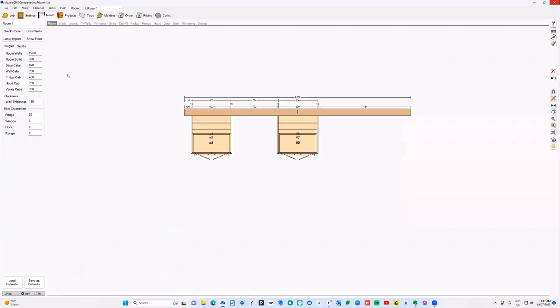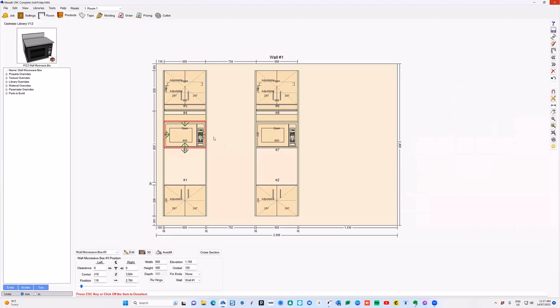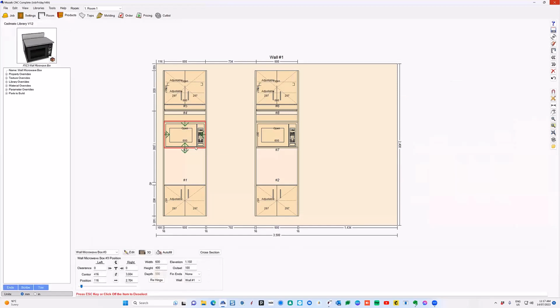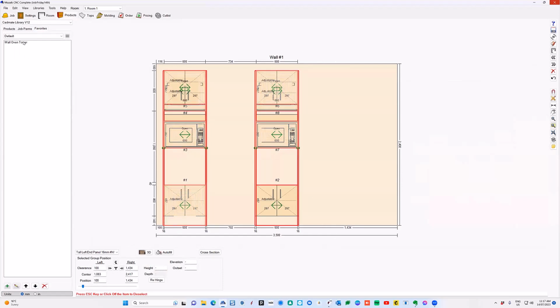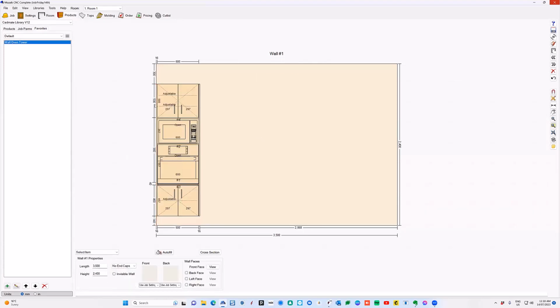So just to be clear there, if I go back and my wall height here is 2400, my soffit height is 300. If in my next job, the soffit height was only 100 millimeters, then you're going to have a difference in the way this product's going to be built. So what you're going to need to do there is rejig your section. So if I was to clear this out and then drag that product back out, what you're going to see is it's still going to come in at what that current height was.